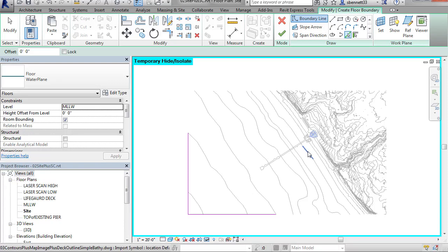If you hover your mouse over one of those contour lines and then press the Tab key on your keyboard once and let go immediately. So you just tap the Tab key real quick and then left click, it will automatically select all of the lines along that contour line. The next thing you can do is type TR again and trim those end segments together.